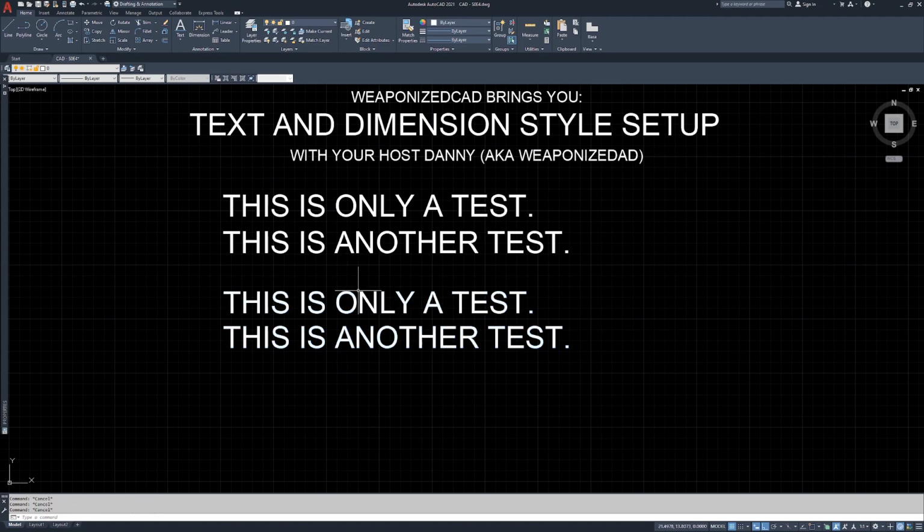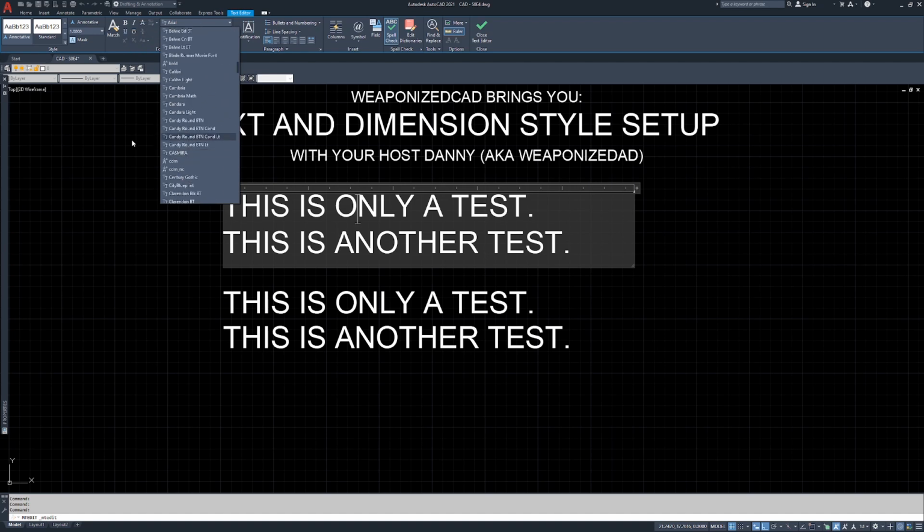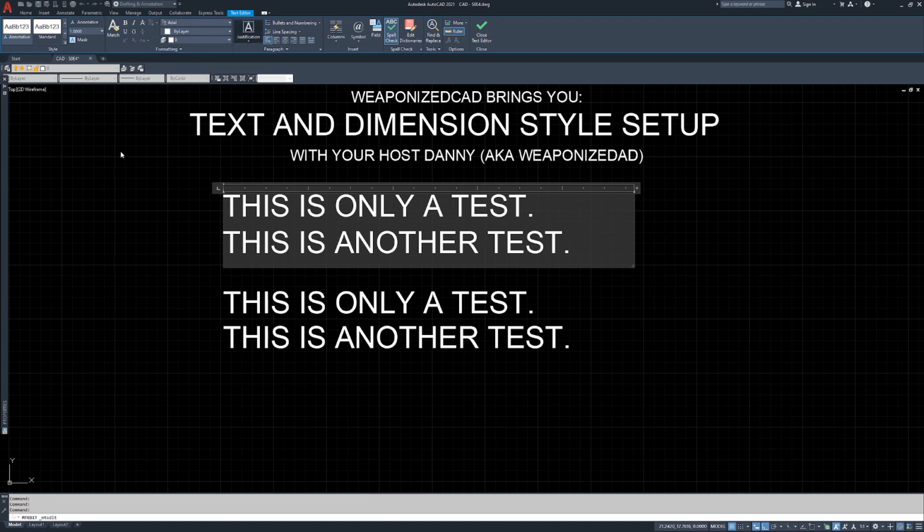So the industry and Autodesk are trying to push us more toward using M-text because it's a lot more powerful. If we wanted to edit this text and we double clicked it, you notice that your ribbon changes. So you have a lot of options up here. You have match properties, bold, italic, underline, overline, strike through. You can change your font in here. You can change your justification. You can change, actually justification is twice. This is for more control as you're working. And these are if you know a certain line needs to look a certain way.